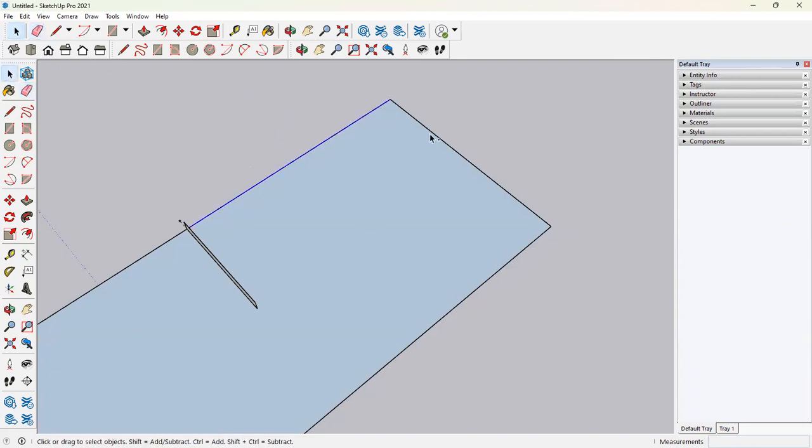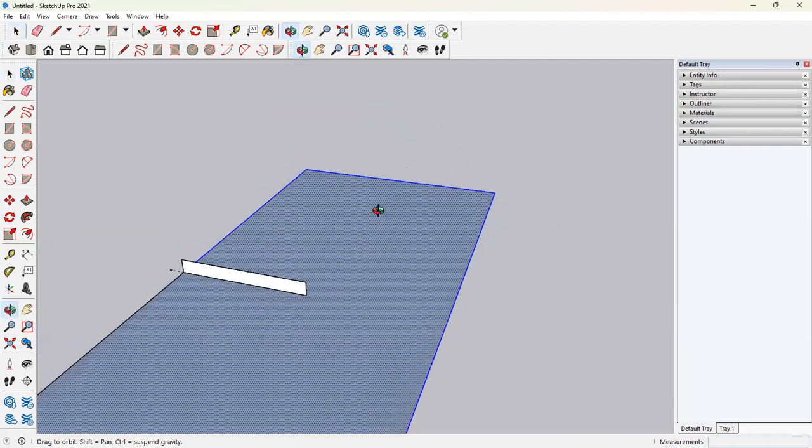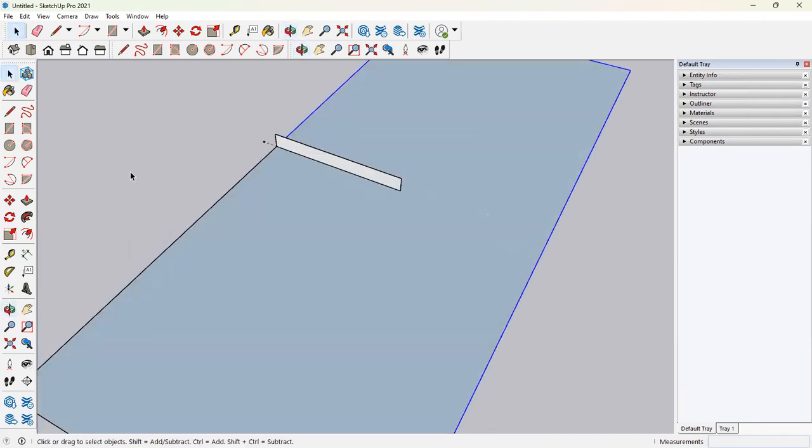So if I select multiple objects with shift. And now if I want to unselect this, what I'll do is I'll press Control. I'll press shift again and unselect the object because I had selected the face. I'll press Control again and I'll select it, if I want to select multiple again. If I don't want, I'll press shift and I'll start unselecting it. And then erase, delete.